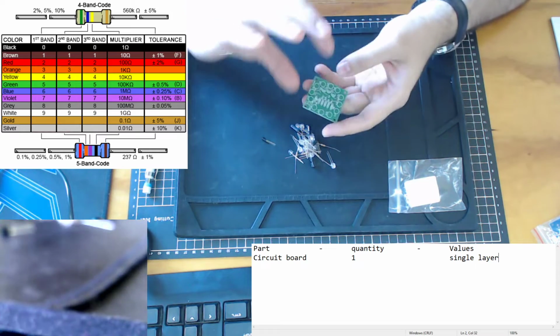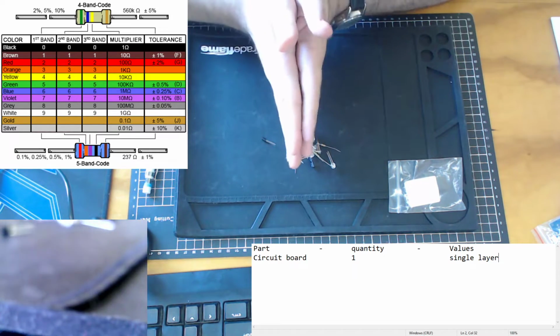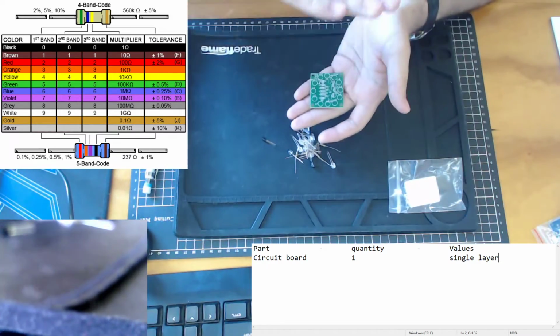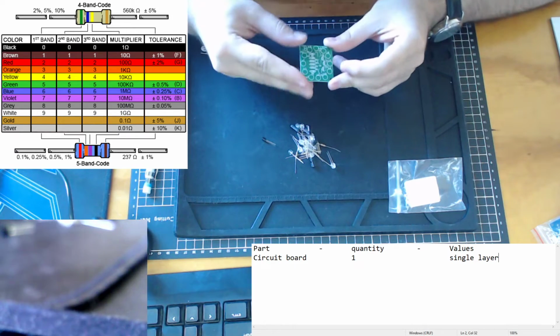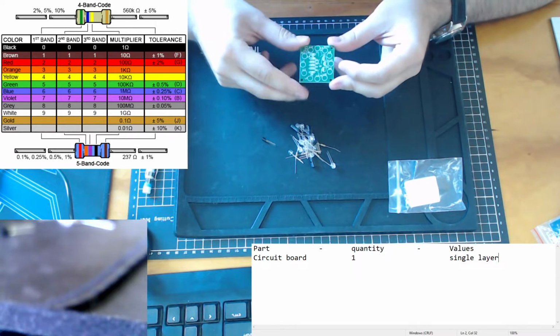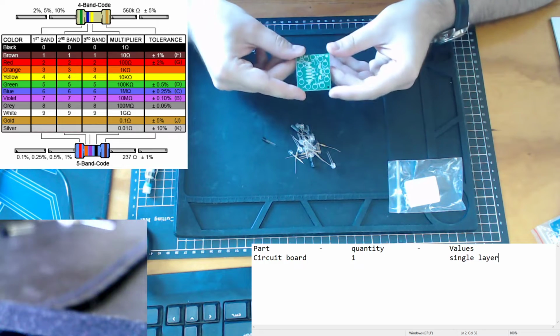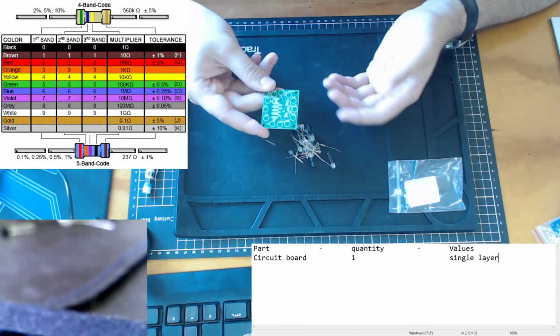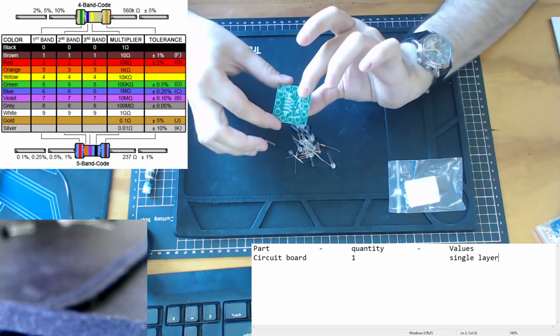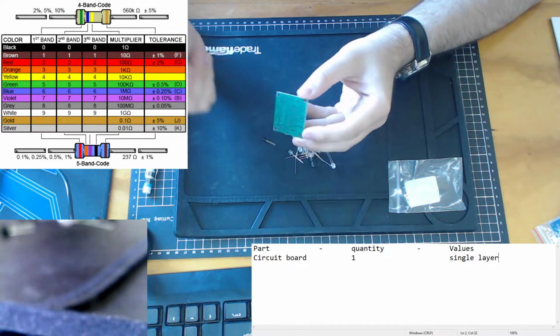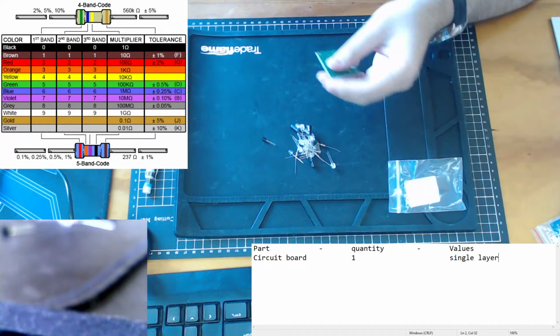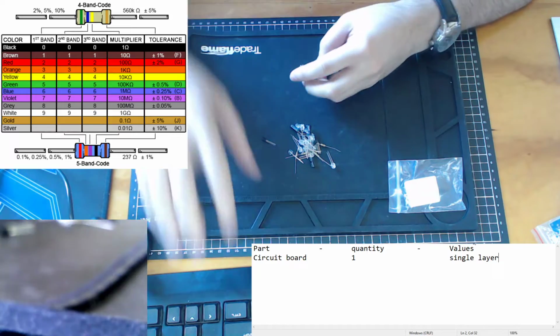More complicated circuit boards can have multiple layers, can be double-sided, but you can also get individual layers of circuit boards together. For example, a computer motherboard, which is one of the more complicated circuit boards that you can deal with, has potentially 7 layers. So you have different copper, and so it allows you to have much more complicated connection wires between them. Alright, so let's move on to some other parts.